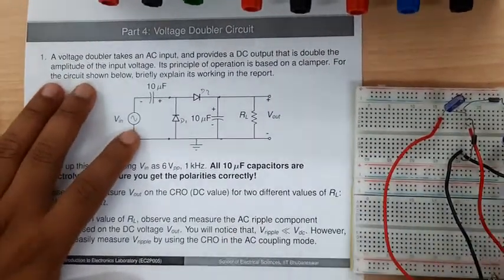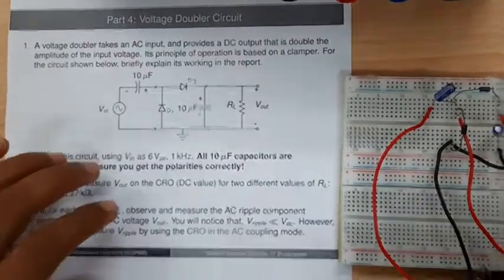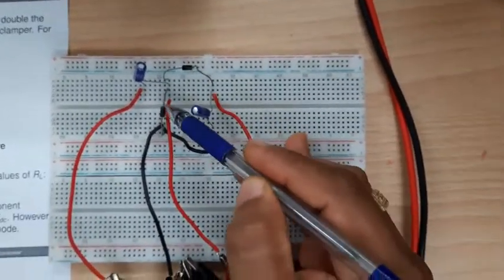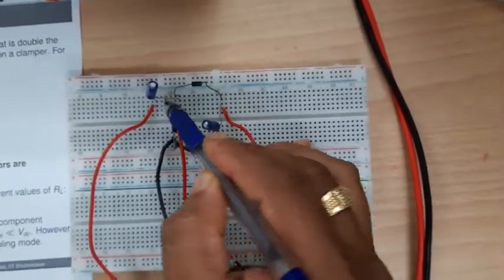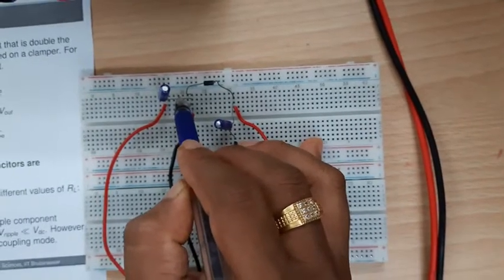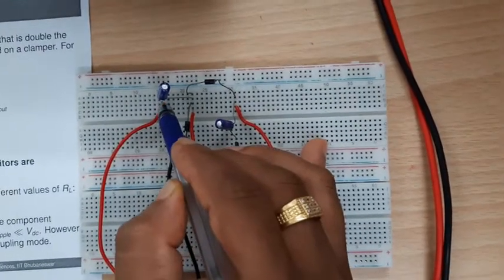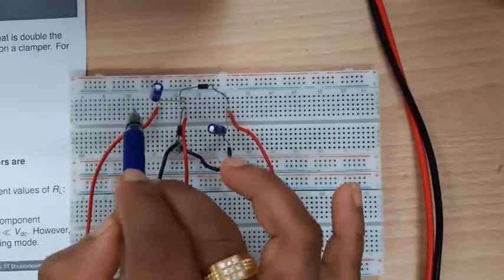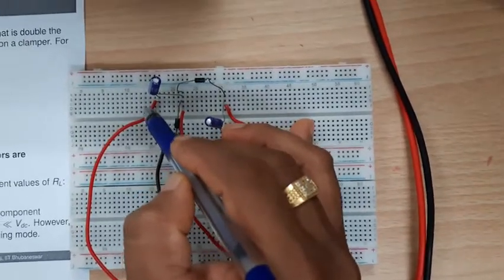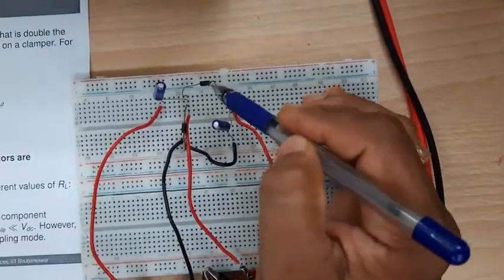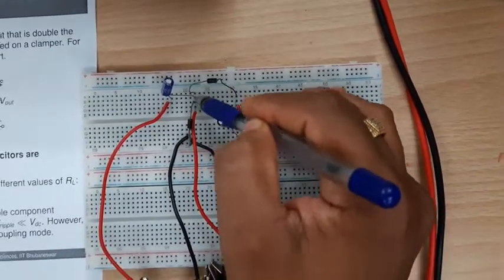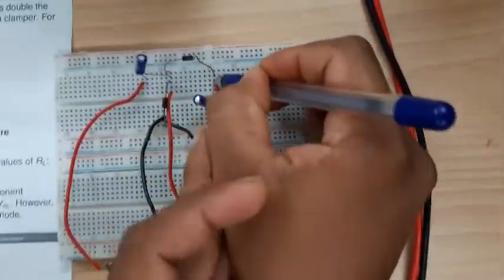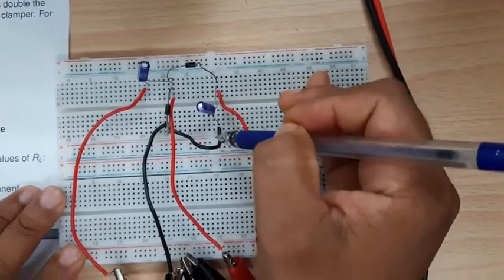That we will confirm today with this experiment setup. Now you see, this is my practical experiment setup where I am using this diode as D1 and this diode as D2, and this cathode I am connecting to the capacitor's positive terminal as per the circuit diagram, and the negative terminal of this capacitor. I am supplying the AC voltage from the function generator. The diode D2 anode is connected to the positive terminal of the capacitor, the cathode is connected to the positive terminal of capacitor 2, and the negative terminal is connected to ground.